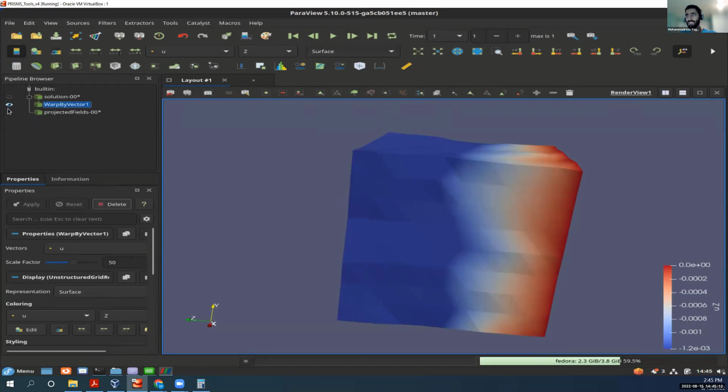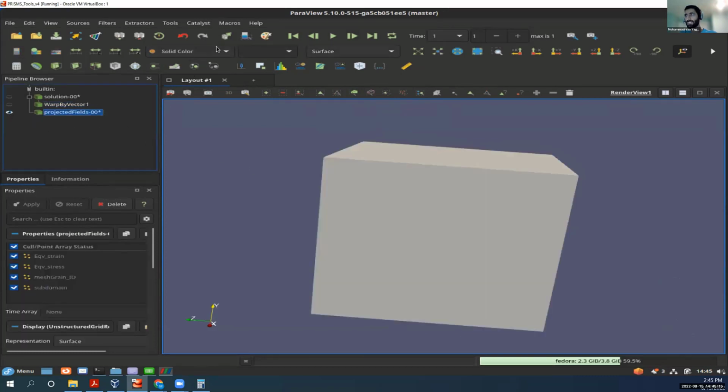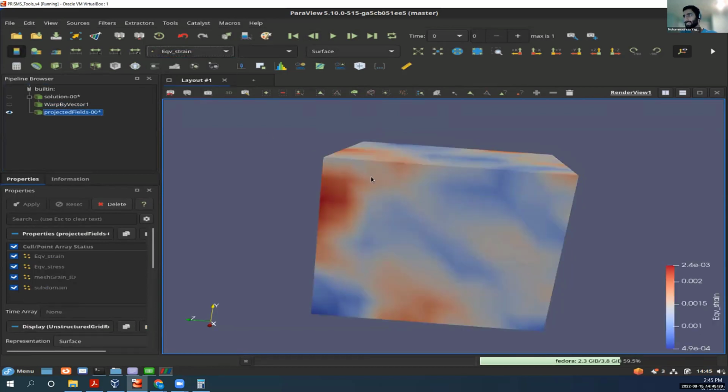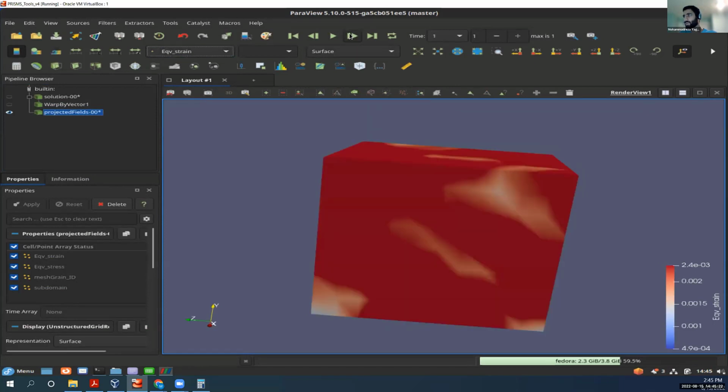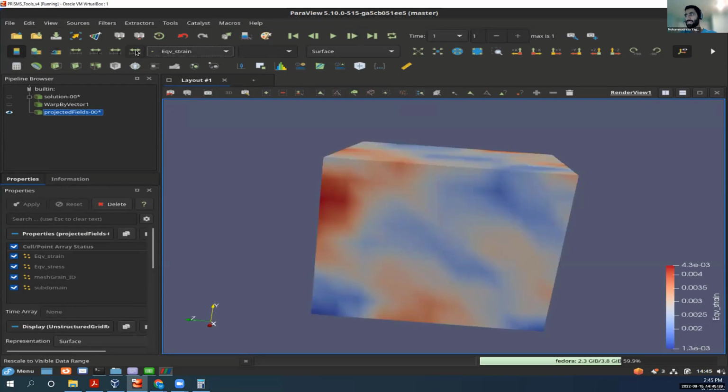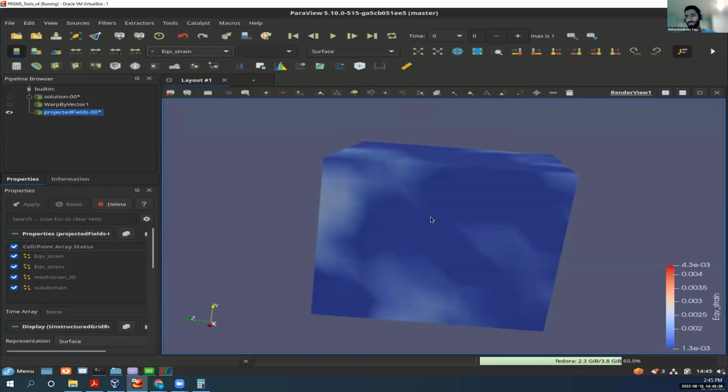And another thing is you can plot, like, equivalent stress, and you can march over the time, and then rescale that. Typically what I would do is go to the last step, rescale that, and then march back to see how it changed. So this is pretty much the basics of ParaView, but as I mentioned, there are a lot of advanced capabilities that I'll try to cover tomorrow.